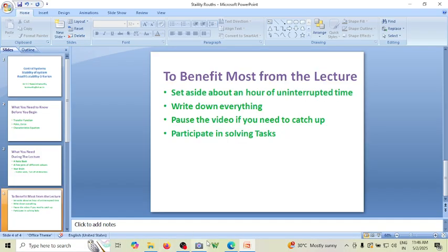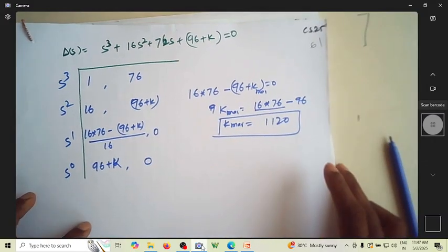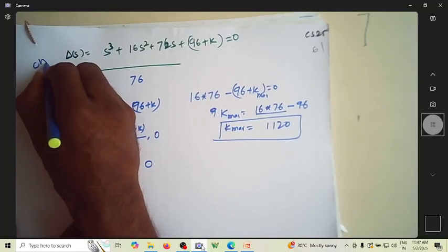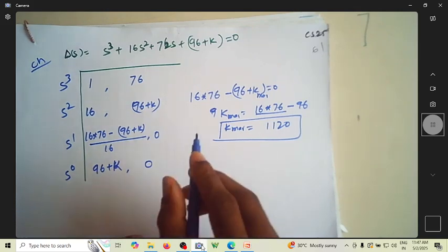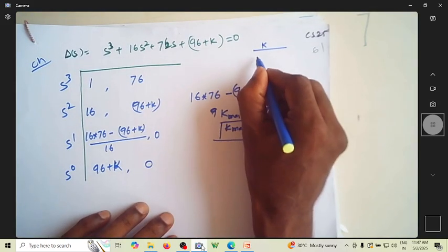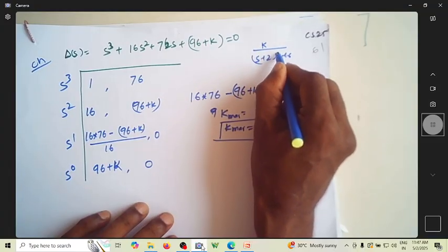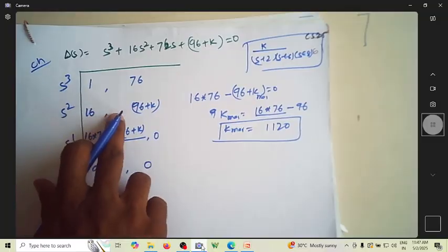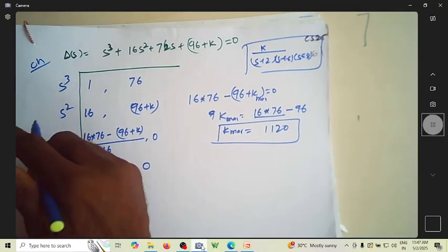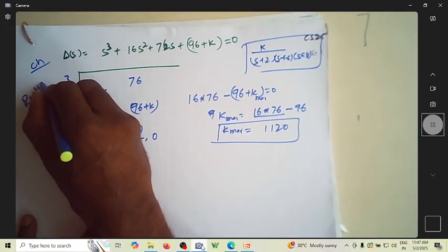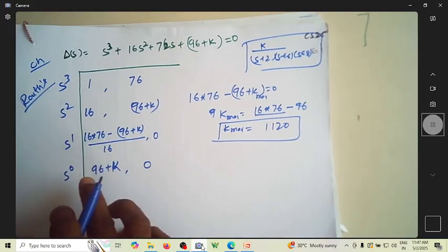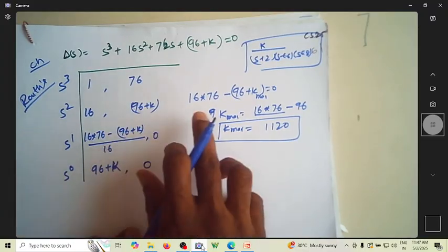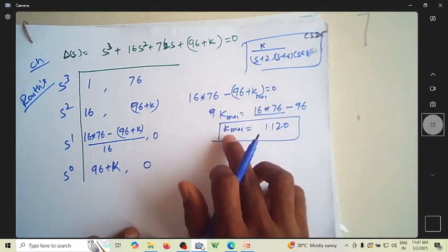Okay, let us continue with the things we discussed in the last video. This is the characteristic equation of the previous system, with open loop poles at s plus 2, s plus 6 and s plus 8. We found this characteristic equation and wrote the Routh's array. This is the Routh's array, and we also tried to find out for what value of k this term becomes 0. We took that as k margin here.